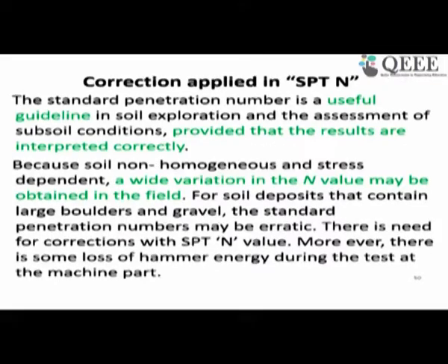Now the number which comes from this test, the standard penetration test, is a very crude number. Although it is very important and crucial, it has to be used cautiously and with some kind of correction. It is a very useful guideline for the exploration, but the result has to be corrected for various aspects like overburden and dilatancy.